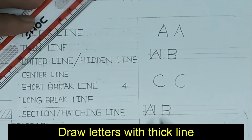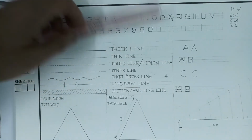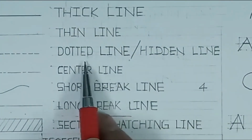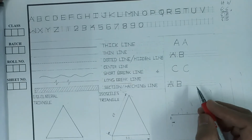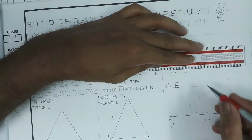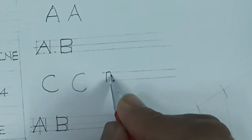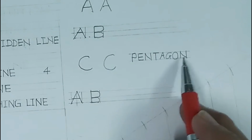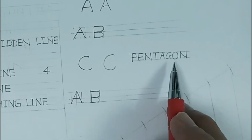Now you might be thinking that if I go on drawing each letter with instruments like this, it will take a long time. No need to bother about this. Initially, only the first time, we have to draw all these letters using instruments, and afterwards we can use the freehand method. Once you are used to drawing these letters, I can show you, if I have to draw, say, the word pentagon, I can draw two lines at whatever height is given, say 4 to 5 millimeter, and within this I can draw the letters. So this is the way. Once we get used to drawing all these letters, it becomes easy to draw them freehand. I hope you understood.